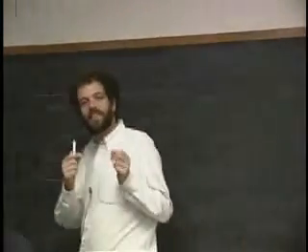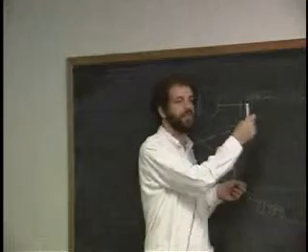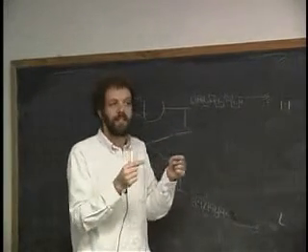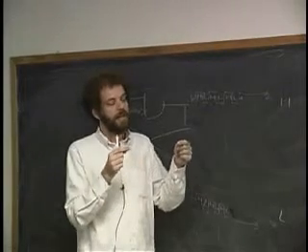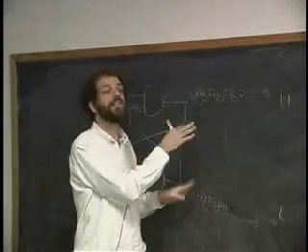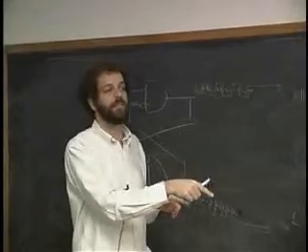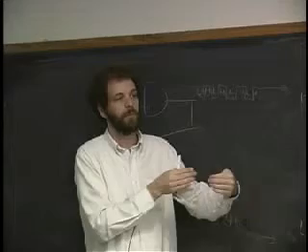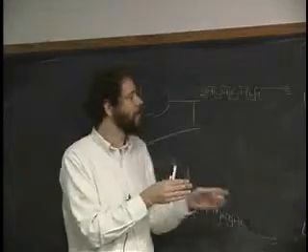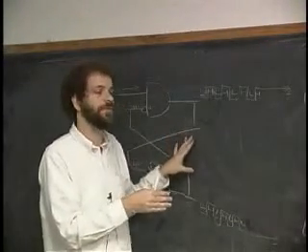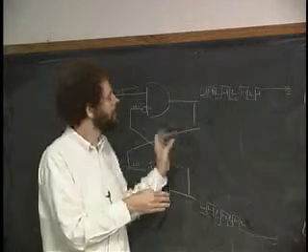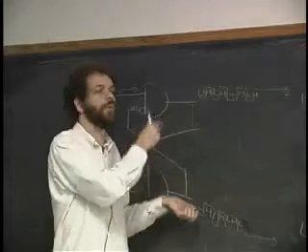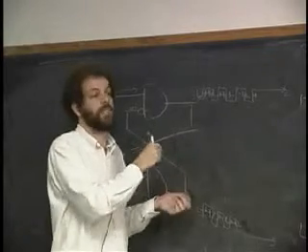That gives you an idea of how the ones might win out over the zeros, or the zeros over the ones. Of course, that's not a way of guaranteeing that we'll get out. We may be stuck there forever. It all has to do with the exact time that we hit each other, exactly where we were with respect to each other. And it is theoretically possible for a circuit like this to oscillate forever if we happen to start it in just the state where it's balanced between going one way and the other in a dynamic sense.